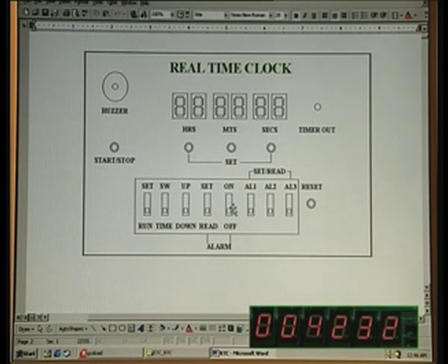And you also have one set and read. This appears to be redundant. It's not really so, because we also need to have the same controls for the stopwatch also. Once again, in stopwatch you have an up counter as well as a down counter. So perhaps if you give a little more thought, you can save some of these switches. But I did not make much attempt at reducing them, because these switches are already available on the hardware that we have already used for the traffic controller earlier.